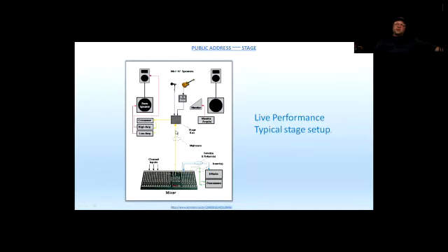One thing I'm going to tell you is that one of the biggest problems you're going to encounter when you use the analog system is ground loop noise. The ground loop noise basically sounds like a 60 hertz hum, like a regular buzz from a transformer, but it can sometimes be amplified. And when that happens, it's a very annoying and sometimes very stressful situation.